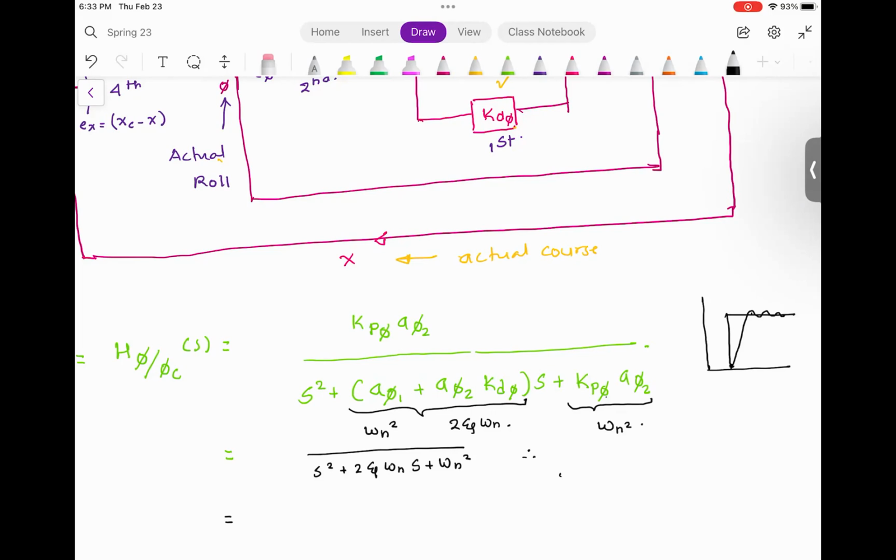So what you're seeing, that your aircraft goes and then becomes unstable, is most likely because of the wind values that you're putting in, or the values of the side slip angle beta that you have put in. So make side slip equal to 0, which means the aircraft is not going like this. The input to the wind value should be 0, and provide a small non-zero value of thrust, and see if your aircraft can maintain level flight for a long time. Your aileron should be small values. Your rudder should be at 0. So try that and see if it works.